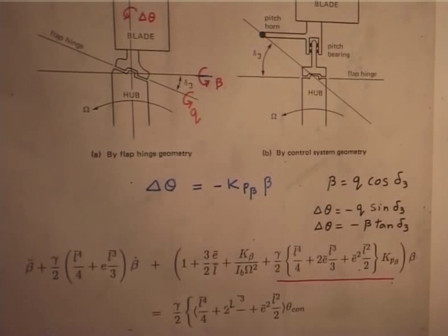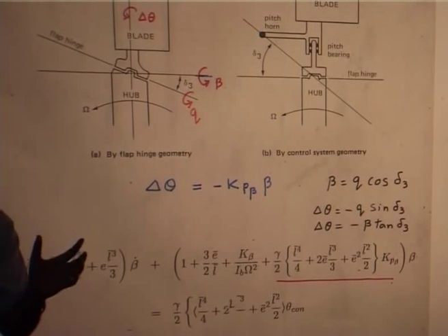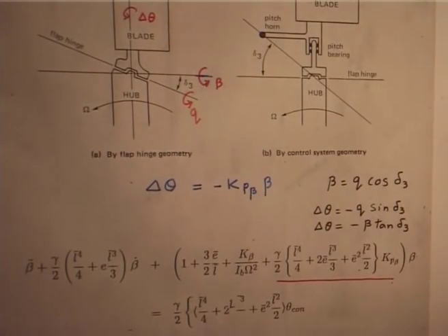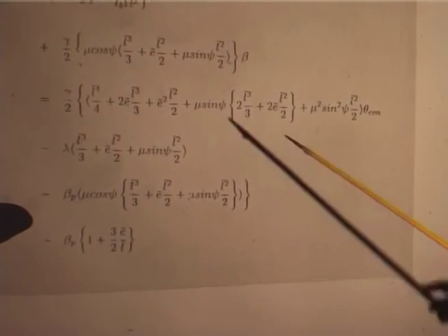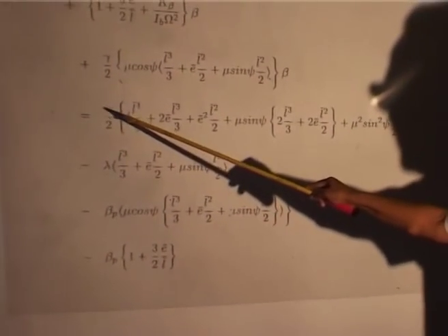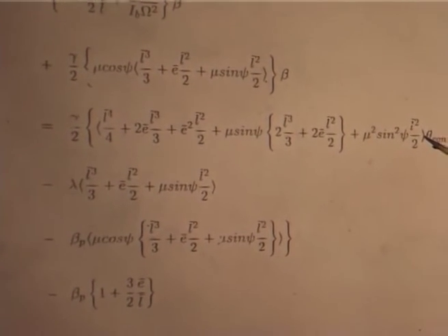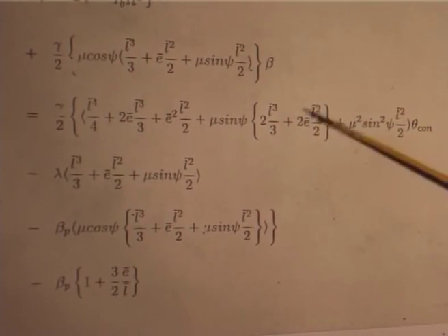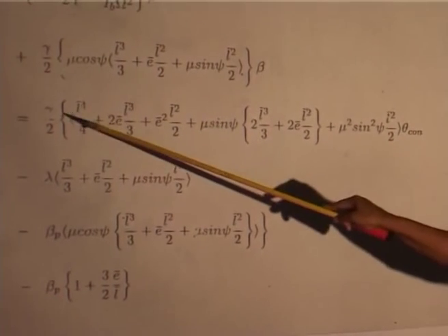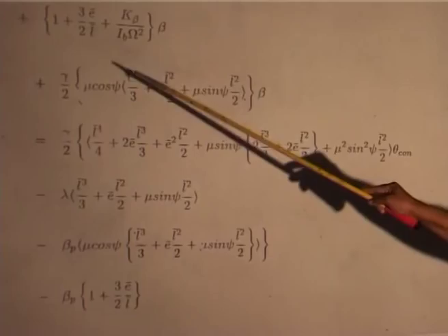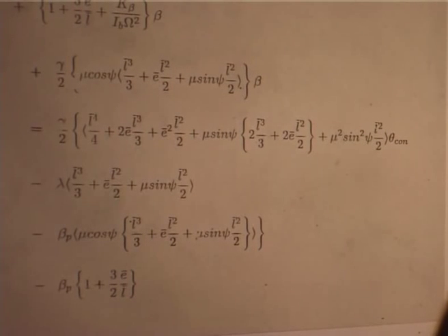because theta has a coefficient, and that coefficient term is basically the aerodynamic term. I will show that equation. See all these terms, gamma over 2 entire term will come. In hover mu will go off, only this term will remain, and that will get added to the already existing stiffness term.